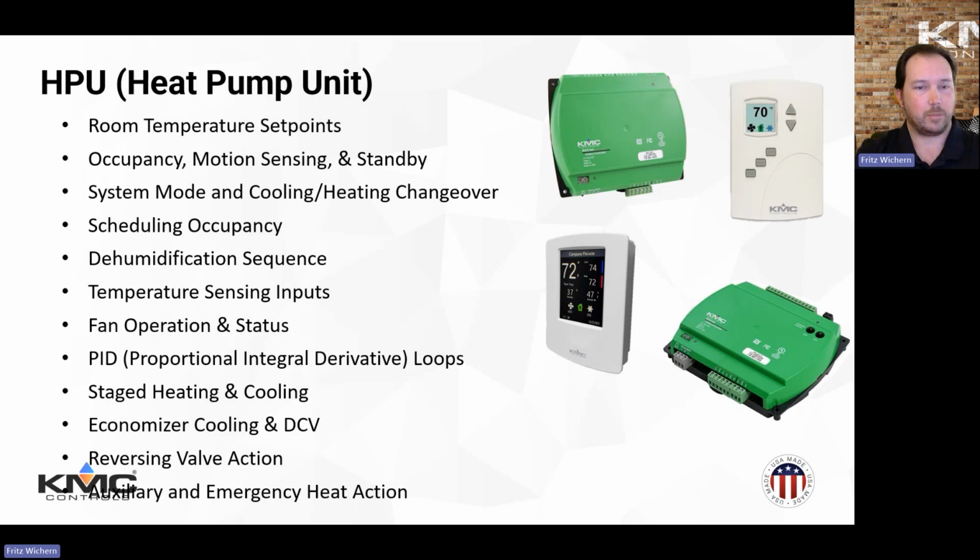And then we've got, again, the economizer. Economizer is enabled when the conditions are met. The economizer actually controls to the larger value of a minimum economizer damper position or the discharge air temp PID loop output that we mentioned a second ago in the PID loop section. If we do have one of our STE sensors with the CO2 connected to it, we can pull in and look at actual CO2 level to adjust the outside air damper to maintain fresh air intake. So you get a little bit of that demand control ventilation tied in with this as well.